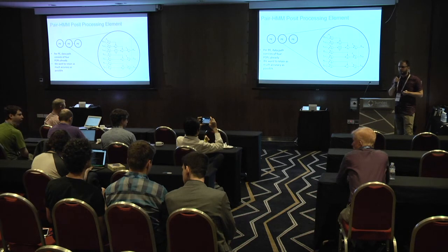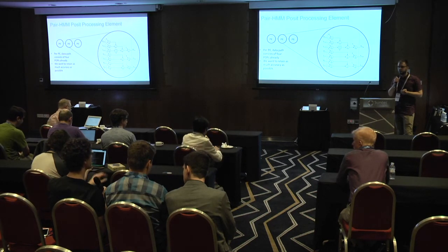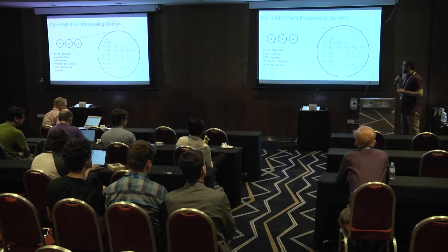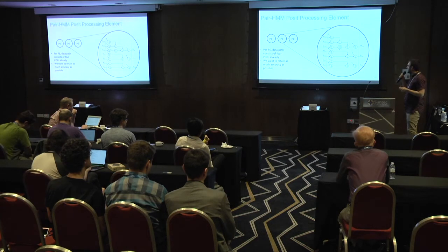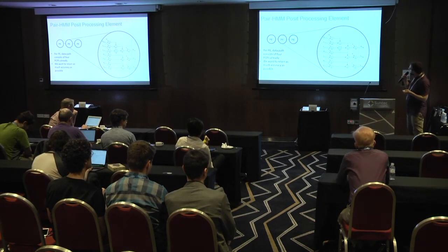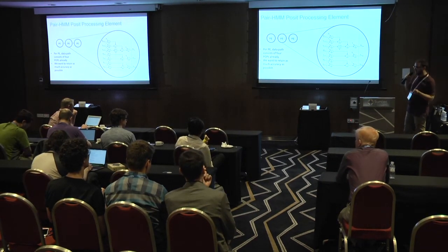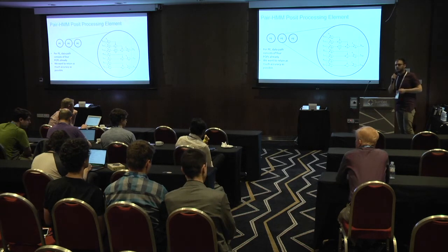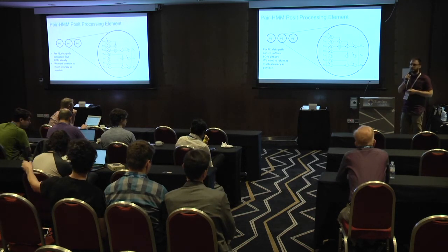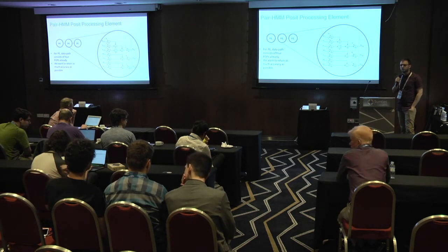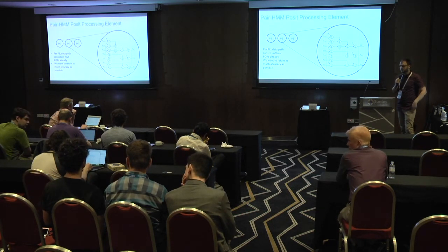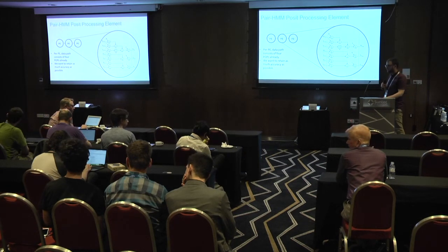How many posit operators do you pack in your FPGA eventually? So I know for this implementation that there were 16 PEs being used, and I think it's about 17 operations, if I am correct here. And then you also have to add the accumulator at the end. That's also an adder and a multiplier.